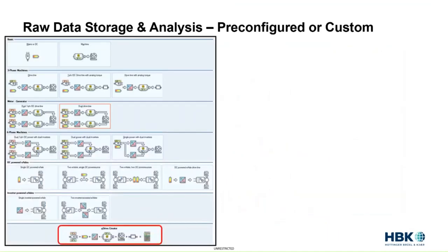So now a power analyzer should also offer a variety of ways to either select from pre-configured setups or even allow you to make custom configuration and automatically create all the necessary power flow and power calculations based on your system's configuration. So in this example, you can choose between a basic mains or DC or machine to 3 to 6 phase machines, motor or generator setups, and DC or inverter powered e-axles, or even map your own custom configuration.